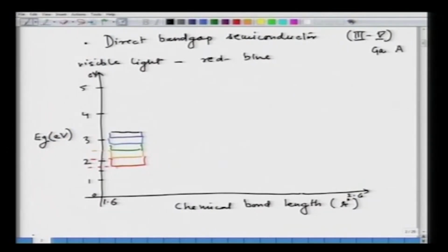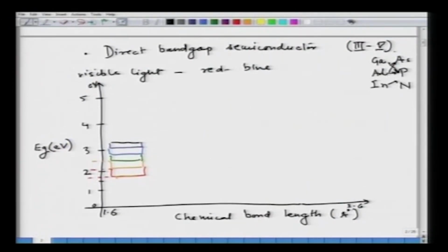So, gallium arsenide. In the fifth group we have the option of phosphide, arsenide and nitride. In the third group we have the option of gallium, aluminum and indium. So, we can do the mixing and matching in any of these combinations, and that gives us the 3-5 system.